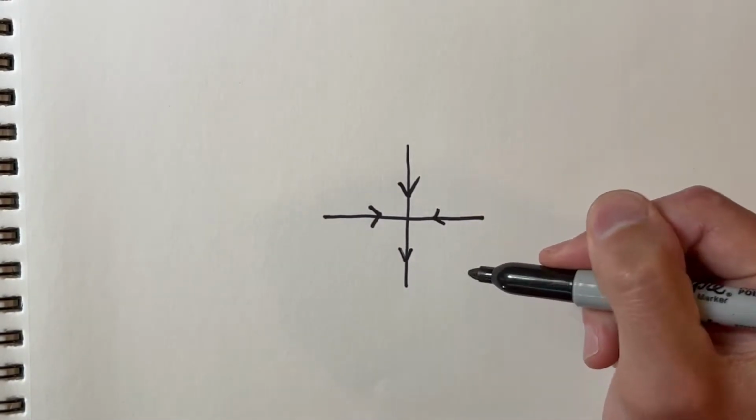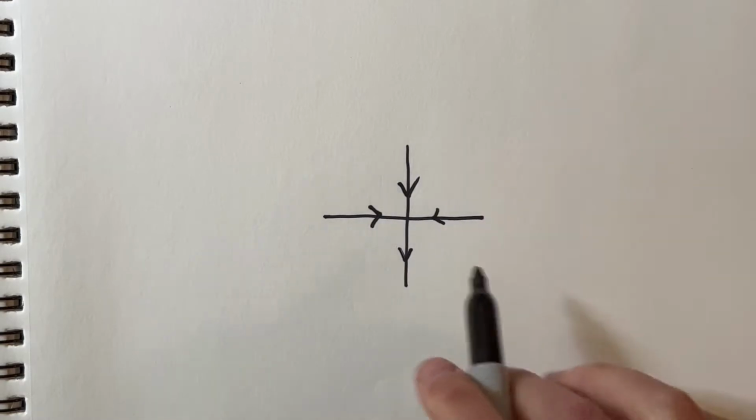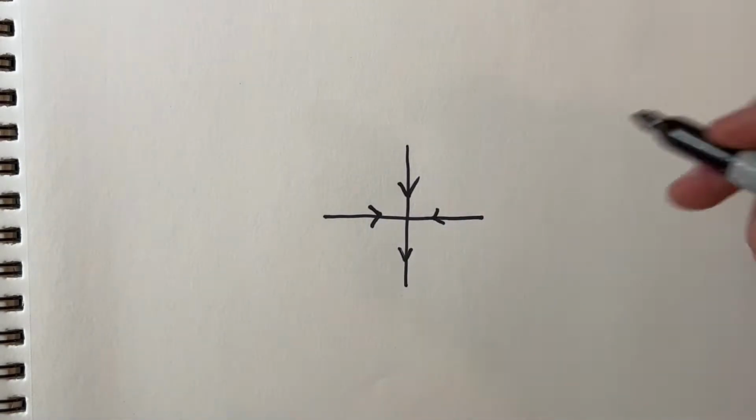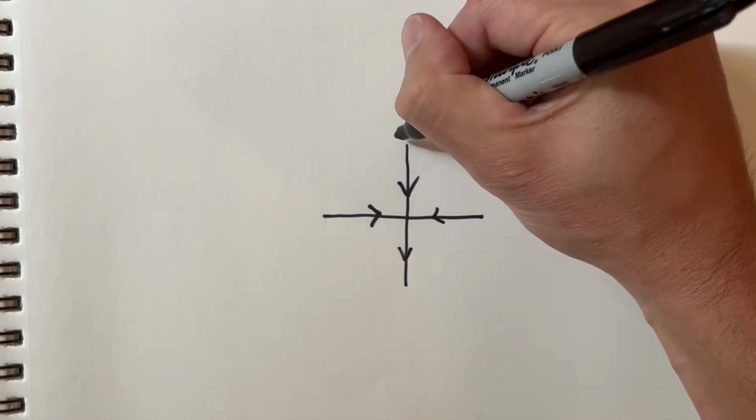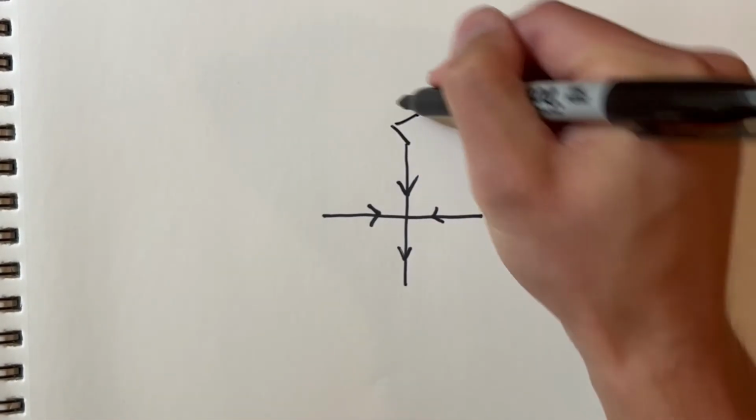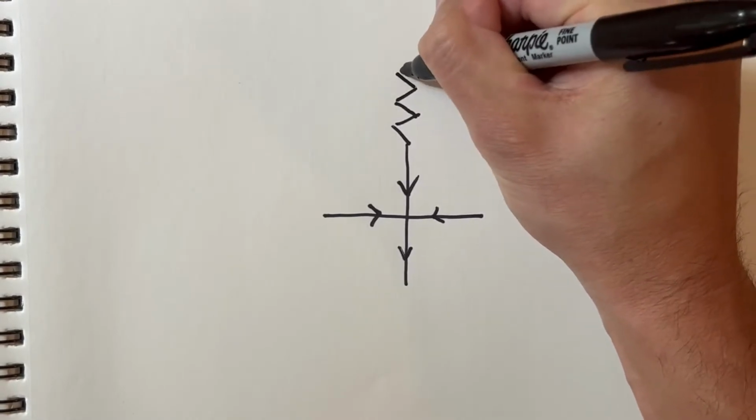Now, we know that we want a little bit of fluid resistance leading into the cross junction, so we end up with the proper flow rates at reasonable pressures. I'll just represent that by drawing a little fluidic resistor in the center. And the same thing on the side channels.